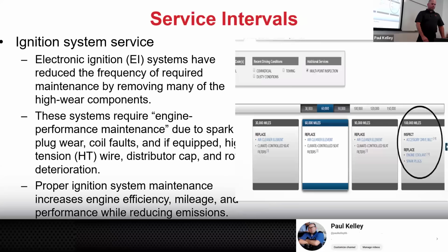All right, so here we go. You ready? Let's go back in time because we talked a lot about how to diagnose the coil unplug, but now we're going to get some prior perspective. If the car came in with a misfire or stumbling, poor idle, poor fuel economy, they'd be like, oh yeah, you need your tune-up. Okay, tune-up: spark plugs, cap, distributor rotor, spark plug wires. If it was an older one, you do the points and the condenser. These were wear items, so we'd be doing them all the time. It's important you understand the perspective. We used to be doing tune-up stuff all the time.